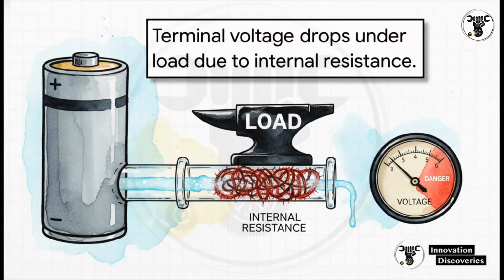We really need to ground our diagnoses in the fundamental math of the electrical system here. And this brilliantly illustrates the exact physics of why this hidden resistance just crushes your battery's performance. Your terminal voltage under load, which is the actual usable voltage your device receives, is equal to the battery's open circuit voltage minus your current multiplied by your internal resistance. In simple terms, the more current your device pulls, and the higher that internal resistance is, the larger the resulting voltage drop. A battery practically never delivers its full theoretical voltage to your device when it's under a heavy load.